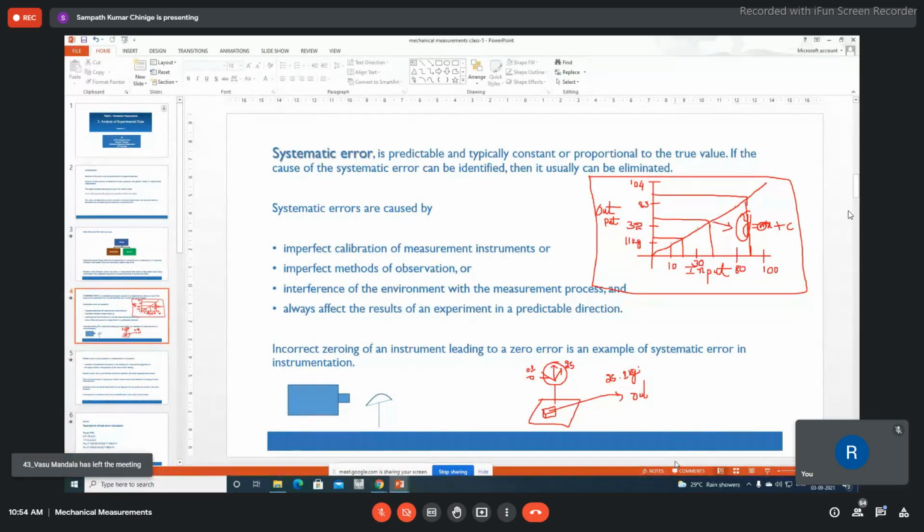So now in that hot water bath, for a 30 degrees temperature, when you heat it to 30 degrees temperature, that is precise. You are taking this thermocouple and putting it into that, and with the help of a data acquisition system, you will measure the thermocouple temperature. Okay, how does the thermocouple measure temperature? There are two junctions, two dissimilar metals. You know that principle, Seebeck effect and Peltier effect.